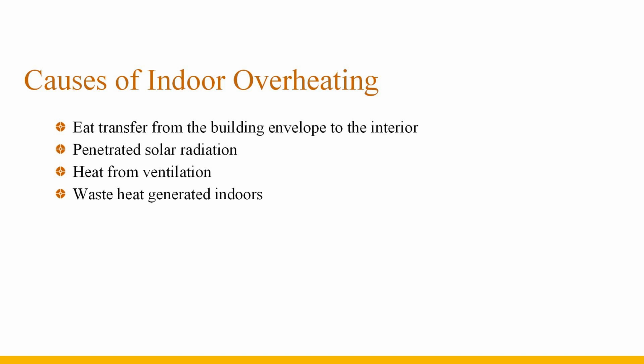Building heat protection is to reduce the amount of outdoor heat entering the room, and the indoor heat should be dissipated as soon as possible. The heat protection design should be comprehensively dealt with, instead of taking measures alone, mainly using heat insulation and natural ventilation, supplemented by window shading and greening.